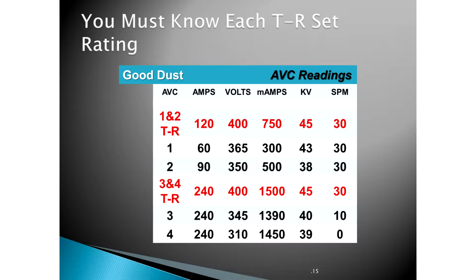And they put the big transformers in the outlet. Why? Because we know precipitators pull the most current in the outlet and the least in the inlet. And for transformers, you want to load them close to their full potential. You want to load them at about 70 to 75% or more of their potential to get them to work right. They'll work down at 10%, but not as well. They'll also precipitate sparking or induce sparking.